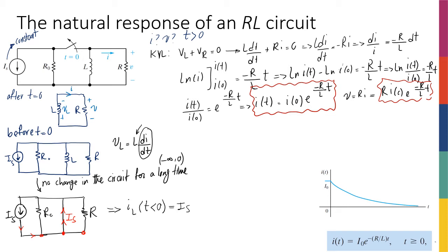The reason was that they cannot have any instantaneous change. They're going to have a continuous behavior, meaning that if I'm looking at the value of the current of an inductor at this moment and a moment from now, the difference is not going to be anything but 0, right? So if I make my time steps as small as an epsilon, there's a continuity in the value of these parameters, the current of an inductor and the voltage of a capacitor. So how do I use this?